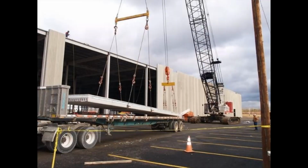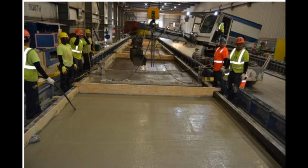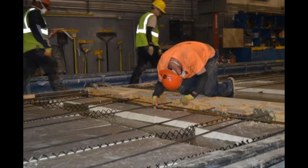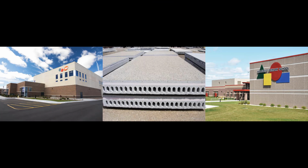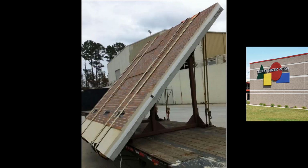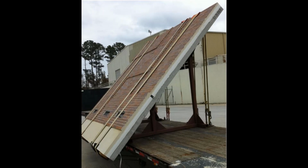It is important to keep the distinctions between panel types in mind when determining a standard wall thickness for a project. Since the panels are cast in a form that is usually several hundred feet long, the thickness should ideally be the same for all the panels on a particular project to avoid excessive setup costs. Occasionally, a designer will select a panel thickness based on the assumption of full composite action, but then insist on thermal performance that can only be achieved with a thicker, more expensive non-composite design. Working with a local precast manufacturer to estimate a panel thickness can ensure design requirements are met with the most economical panel. There are also dimensional considerations that you have to take into account.